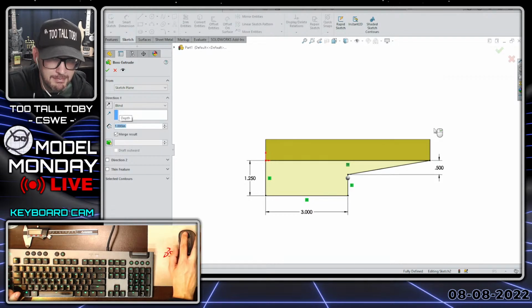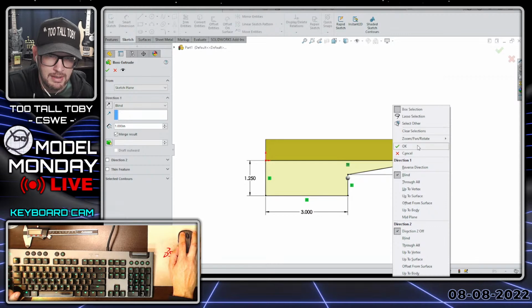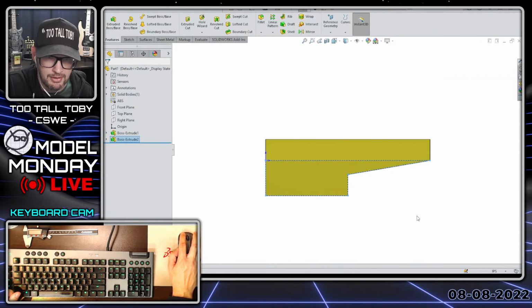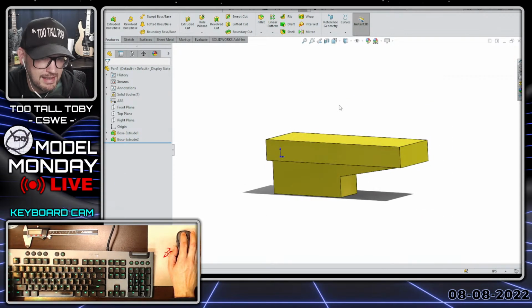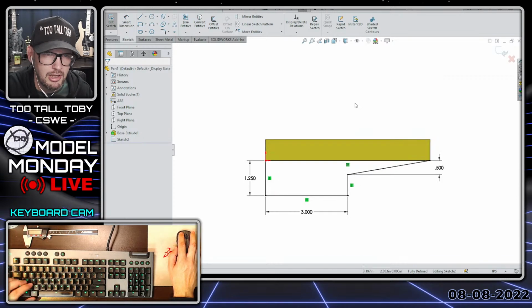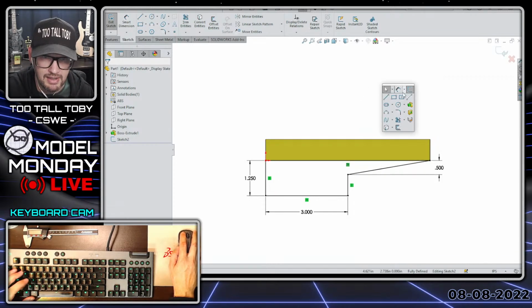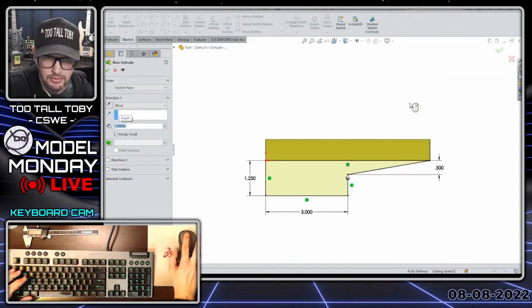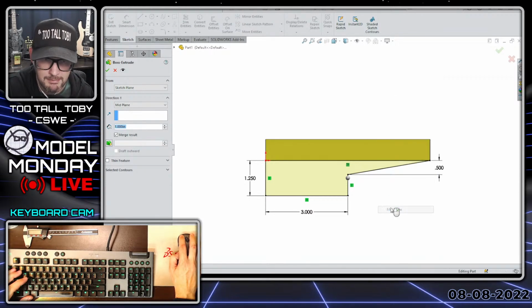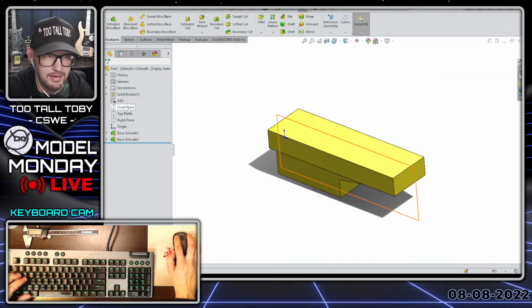Now I can go back to my mouse, right mouse button, mid plane, and then right mouse button again. Now, in that case, I kind of talked through the whole process, but in real time, it might look something like this. S key, extrude, 1, enter, right mouse button, mid plane, right mouse button again, and you're ready to move on to the next feature.